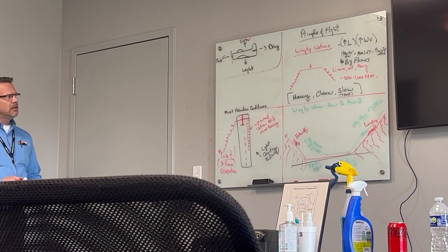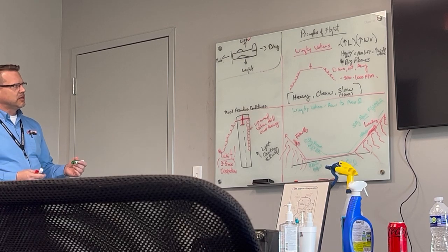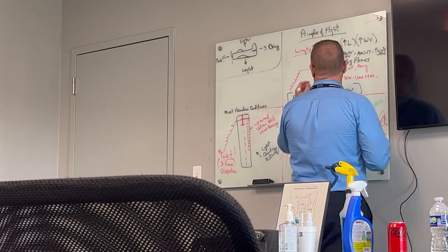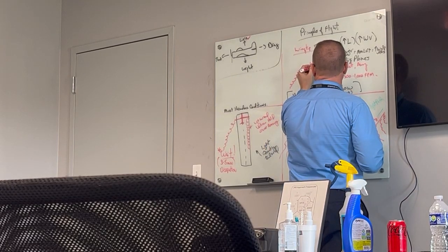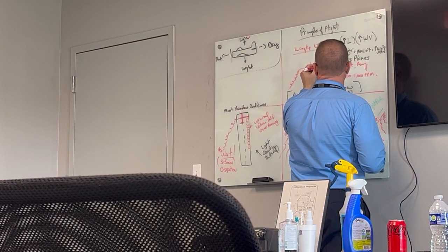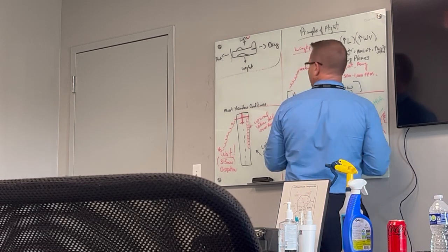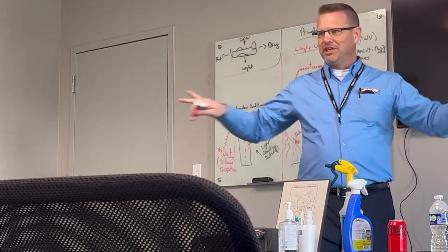So the clean, basically is, so these wingtip vortices, what they're doing is, because it's trying to get to the high pressure air, I kind of drew the arrows where it's straight. The airflow is actually trying to make its way out to the wing, because it is bleeding off the wingtips.